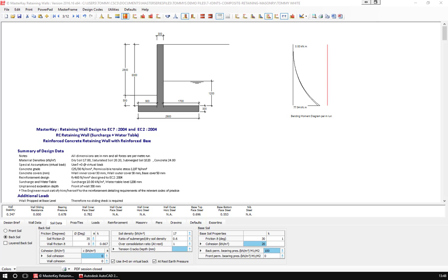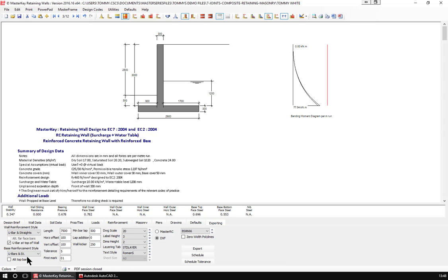Somebody's asking, and it's a very good question, Gary, can you restrict the bar length in the scheduling? That is, when we go to export, to 6 meters. Well, the simple answer to that is, obviously for the longitudinal steel, you detail it for less than 6 meter length. For the other bars, you just would make sure you're using new bars to make sure that none of your bars' overall lengths get bigger than the 6 meters.